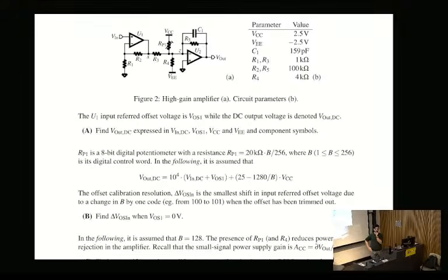When I read some of your lab reports, it was pretty good. I saw you guys talk about this. So could we just measure it directly at the input, the offset voltage? No. Why was it difficult? So small. So what did we do instead? Yes. So we measured it at the output. We'll put a large gain on the amplifier, and we just measured it at the output because then it was a much larger signal. And then we didn't trim it in the lab, but we measured it that way. And then we just divided it by the gain to tell us what it was at the input.